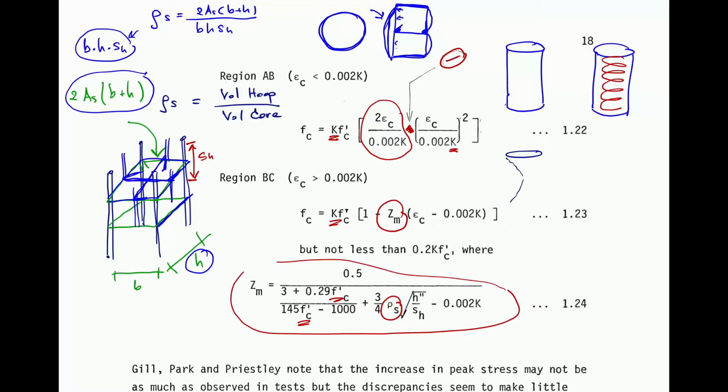You get the hourglass shape that we talked about last time, because as it is not confined, this part just falls and splits. It forms the maximum tensile stress plane, so the concrete cannot bear that. It cracked and fell like that. It does not actually fail by compression. The failure plane is from the tensile stress.